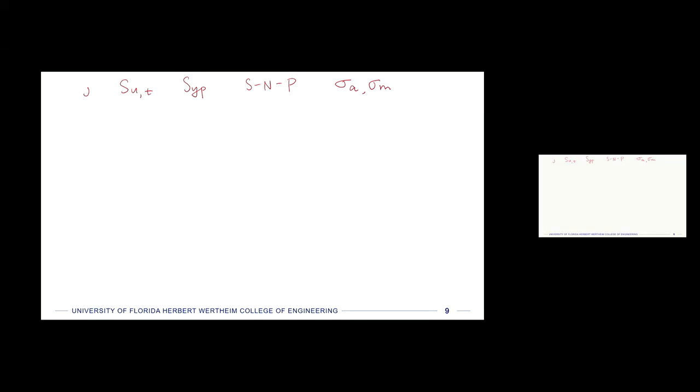Okay. So if this is what we're working with and we really don't have anything else to go from, we have to use a relationship in order to go between these things such that we can get back to the S-N curve and our sigma_N, our fatigue strength at N cycles. One common way to do that is to follow Mr. Goodman, who proposed a linear relationship between these.